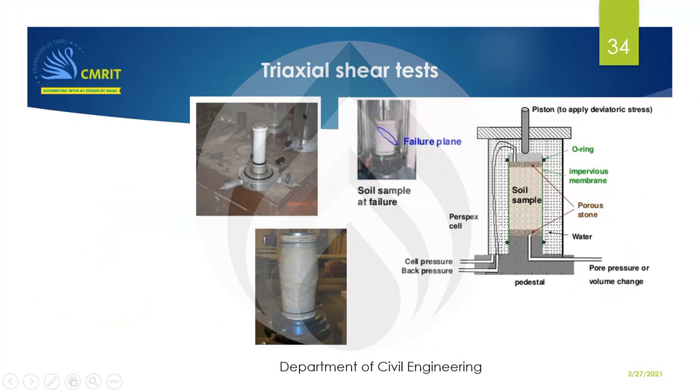So this is a shear test, the triaxial test. You can see the sample. The advantage, as I told you, is that in the triaxial test we keep the sample surrounded by water; the dots here represent water. We do the test in such a way that the soil is in the weakest condition, so we can saturate the sample, which is not always so.